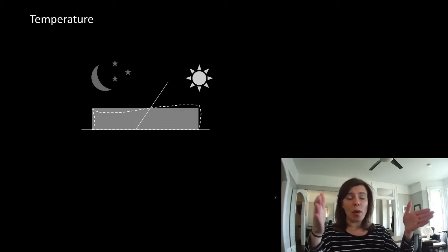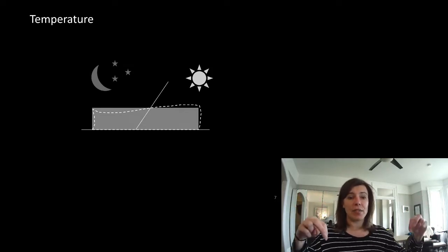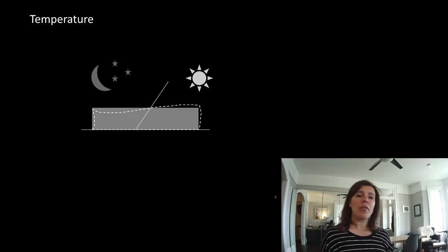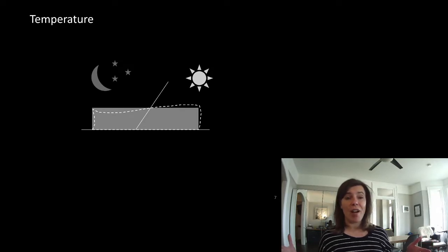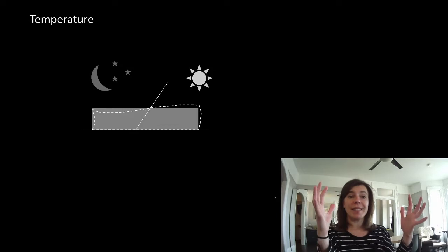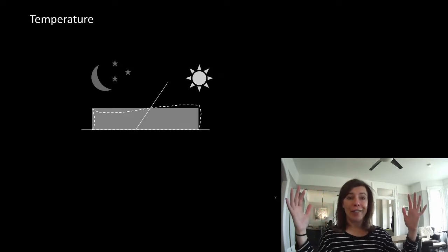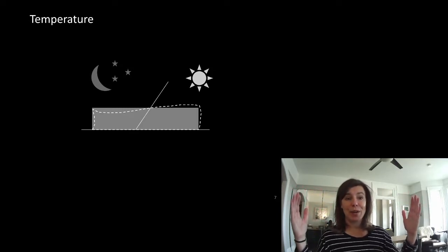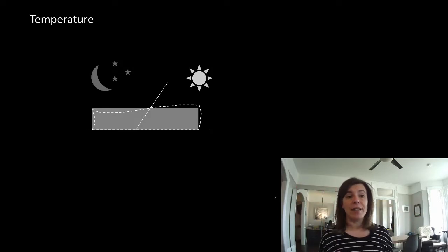It was just sitting where it was supposed to be, but it was the end of the day and they didn't have time to put the anchors in. So everyone went home, no big deal. It was a sunny, warm fall day, and then it got very cold overnight, and the steel contracted, and it wasn't long enough to span to the piers that it was supposed to be on, and it contracted and fell down. Now, it was overnight on a construction site, and no one was there. Luckily, no one was injured.